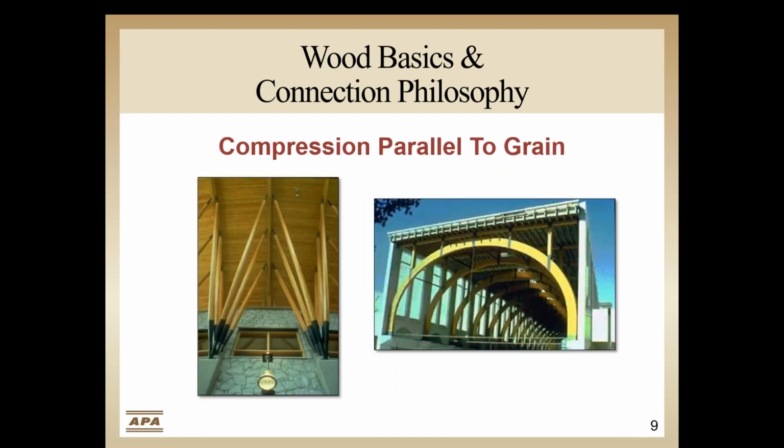As we said, wood grain is strongest and likes load applied as compression parallel to the grain. Structural designs that capitalize on this idea are very economical and attractive and consistent with wood's heritage of the tree and the forest standing tall and strong. Moreover, compression connections of wood are usually the easiest to design and detail.